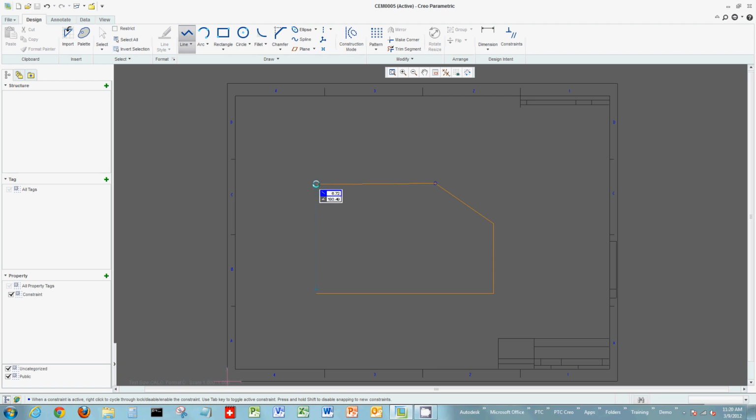So what I'll do is accept this constraint itself, and then I'm just going to go back and tie this to the very beginning to create my shape. Now I can display those constraints here within the actual model itself, and as I click on entities or hover over entities, I see those constraints appear. Very similar to what you have in Parametric, these are all activated on the fly. You can remove or delete those if I choose within the element.